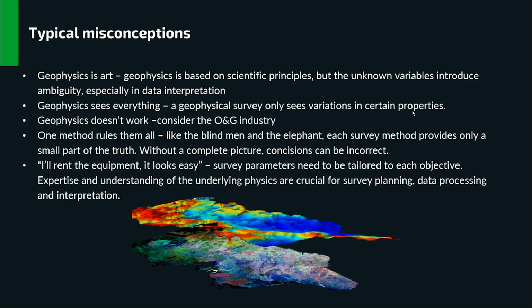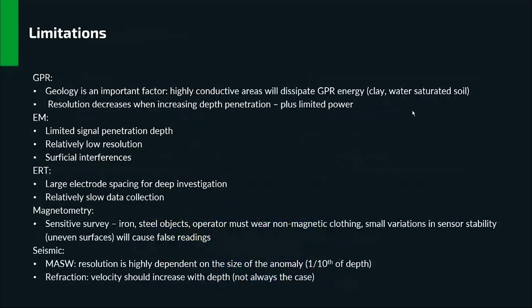A few limitations. I'm just going to mention maybe one for every mentioned method. GPR: the conductivity is one of the biggest issues, and the resolution decreases over depth. Highly conductive areas will not work for GPR, especially clay-rich conditions. In terms of electromagnetic methods, kind of the same applies, but also superficial interferences can be problematic. So if you have an area that needs an electromagnetic sweep, it needs to be cleared in order to get